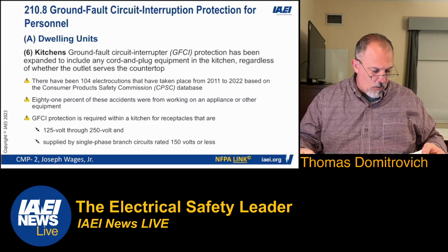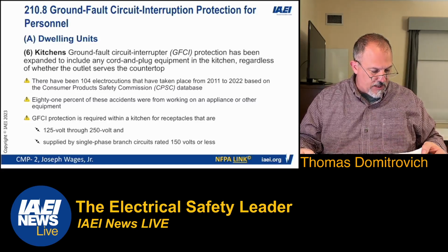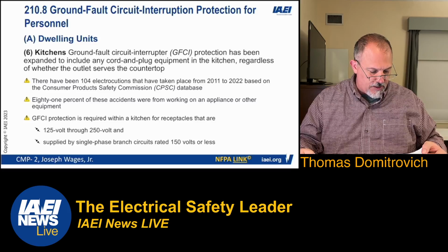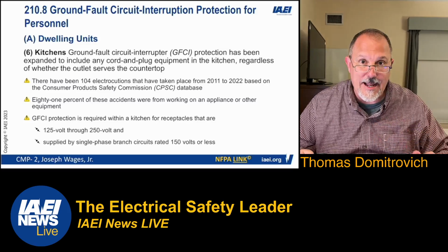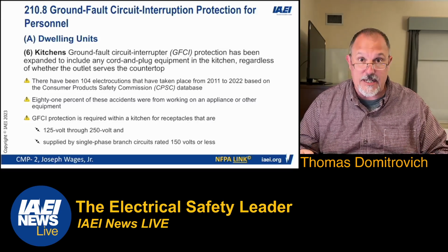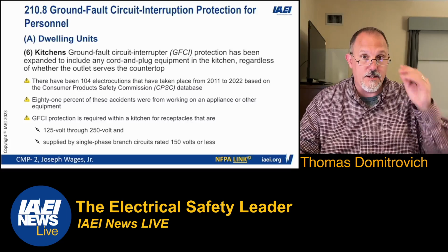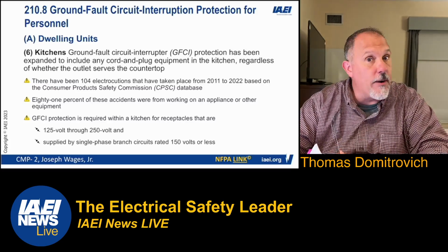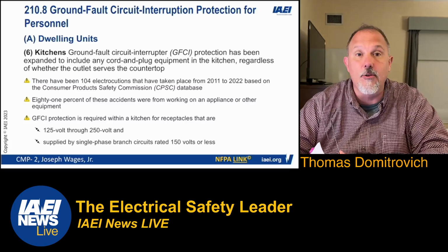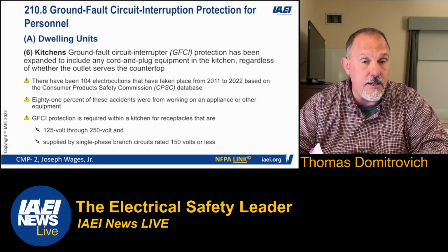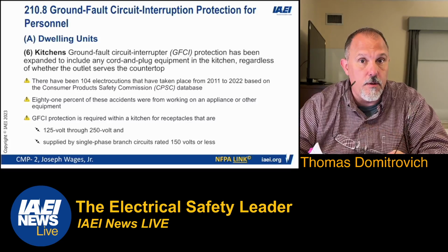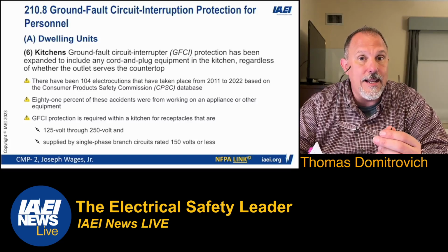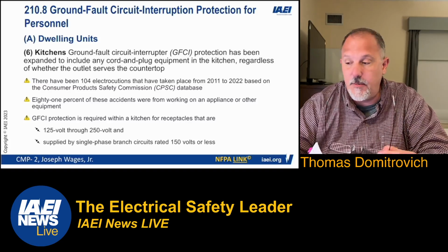We say all 125 volt through 250 volt receptacles installed in the following locations and supplied by a single phase branch circuit rated 150 volts or less to ground. That's any ampere rating receptacle in that kitchen. So that hits anything that's plugged in, refrigerators, if you plug in a range, that's going to need to be GFCI protected. Any receptacle that is in a kitchen needs to be GFCI protected.